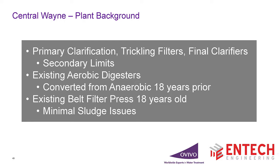The old plant had been a primary clarifier, trickling filters, straight secondary limits. They had existing aerobic digesters that in 1990 had been converted from anaerobic to aerobic. But it wasn't a very efficient design. They weren't covered. They were small little rubber membrane diffusers on the bottom of the tank, a lot of back pressure, just didn't work real great. There was an existing belt filter press that was almost 20 years old. They didn't have any real sludge issues, but again, straight secondary limits, not really removing a lot of material from the wastewater. Next one, Brian.